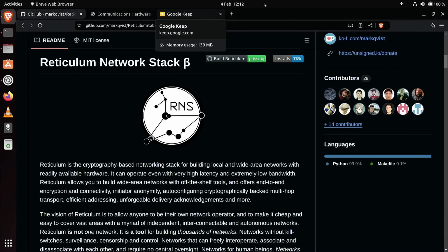In this video I want to show you how to install the Reticulum network stack program, which is called RNSD in fact, and I'll be using the command line. Sorry about that, but it's a command line kind of operation here. And what I want to do is to show you quickly how to configure it simply and get it working with a radio node or an RNode that will use the LoRa protocol on 868 MHz in Europe for wireless communication of data.